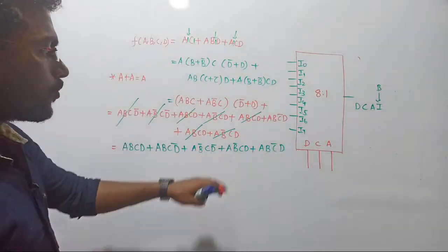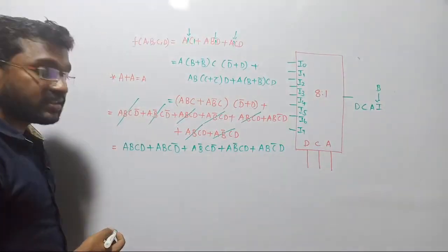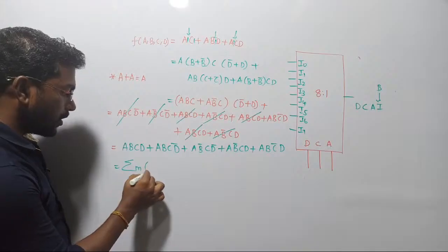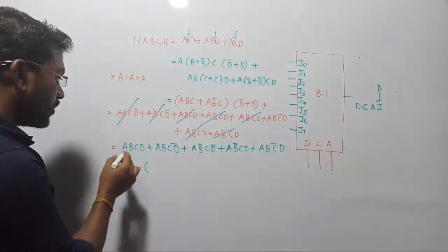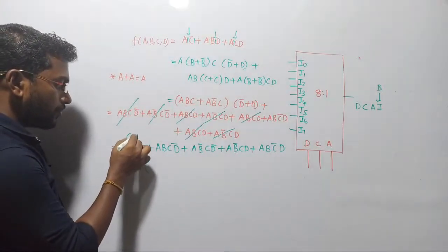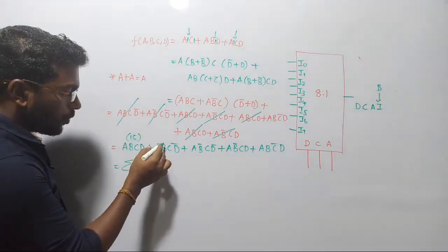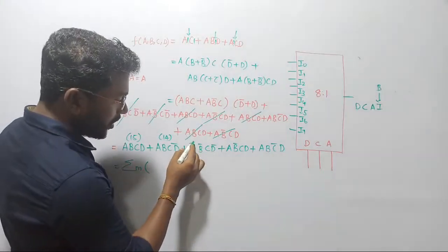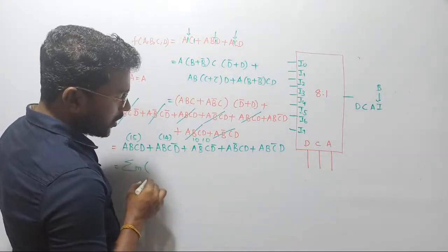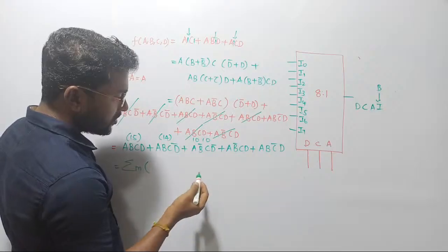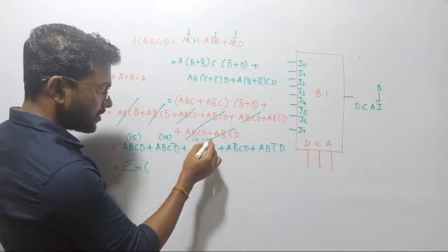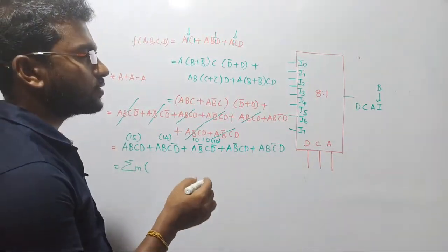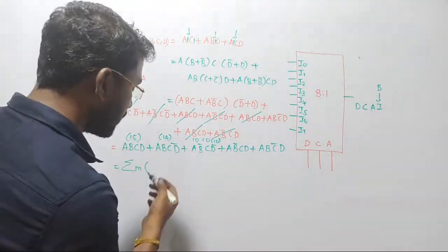Totally 1 2 3 4 5 variables are available. Let's see its decimal equivalent first of all, right? So let me write them in min term format. Let's consider first A B C D 15, 1110, that is 14. Correct? Next, this is going to be what? 1010. Its equivalent is what? 1010. I think that is 10, right? That is 1000, 1001, 1010. Yeah, that is 10 only.